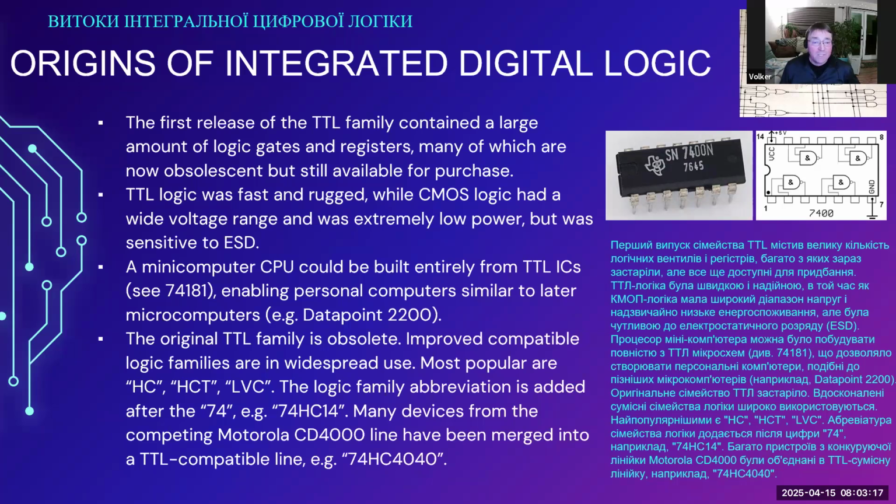I'm continuing here. TTL logic was fast and rugged. CMOS logic had a wide voltage range and was extremely low power, sensitive to ESD. The old CMOS logic was very low power even by today's standards, but the original CMOS logic was not fast at all.